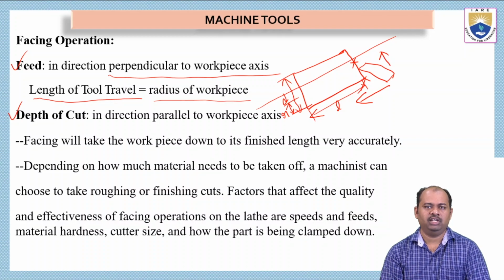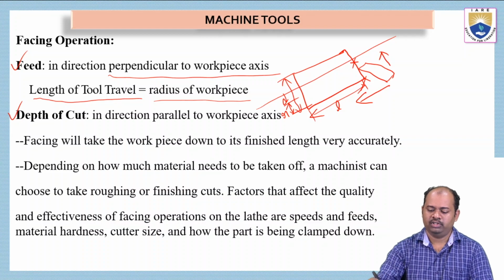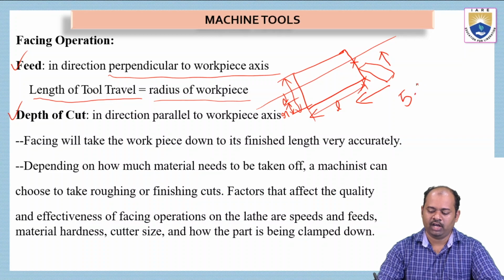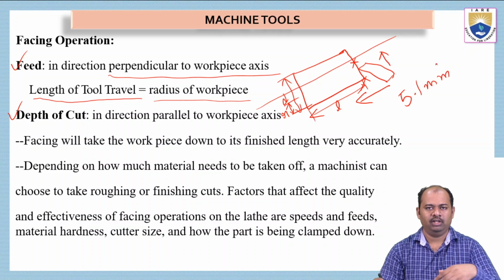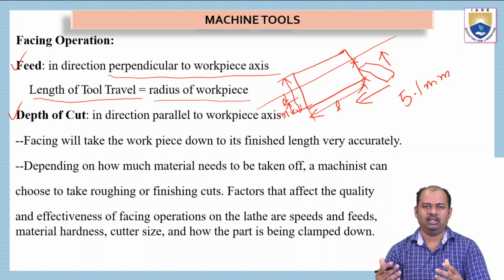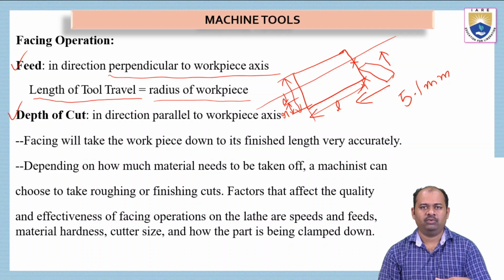Some human errors will be there, which may lead to dimensional inaccuracy. That is why we have to give some extra values. That means suppose if I want to make a cylindrical bar of length 5 mm, I will always prefer to have 5.1 mm, because I will send the information to the manufacturer or the machining operator to machine a cylindrical rod of a dimension 5.1 mm, so that even if some errors happen, I will get finally about a 5 mm workpiece. Okay, this is how we have to always give the dimensional safeties, which will be covered by some errors.